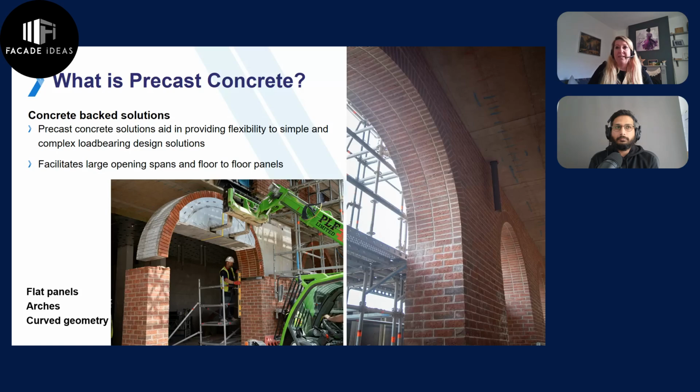It's a very deep soffitted arch with tracked, stack bonded brickwork that's been pre-manufactured in the factory and then delivered as one whole unit to site. As part of my work, we have to provide solutions for all manner of things, and that does include installation. With this project, we couldn't install those arches from above using a crane, so we designed a former that would assist in installing those quite heavy arches from the ground, bringing them in safely and securely.